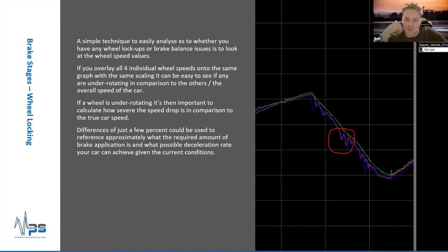very close to that would be your peak amount of brake application, whether that's pressure, whether that's pedal travel, etc. You know, right, at this point I'm probably pulling 80 bar, so 76, 77 bar would probably be my target for this point in the braking phase. So with a bit of data collection, you can quickly map out the physical capabilities of your car. And then if you look at a lap in isolation and you aren't matching these targets, these limits, you can quickly suss out an area of improvement for next time you go out in the car.